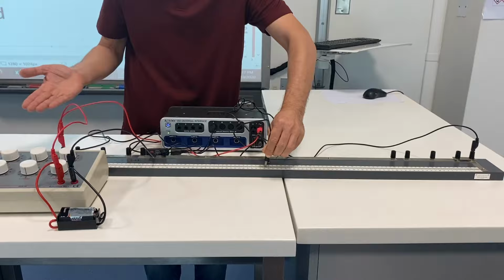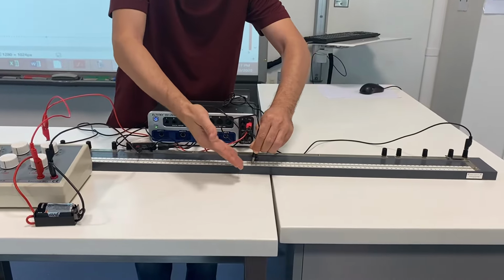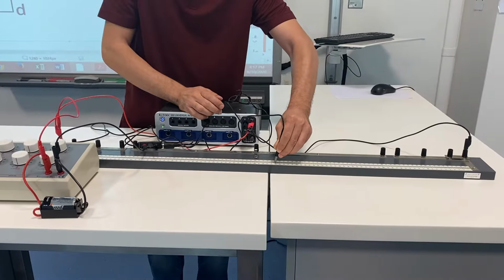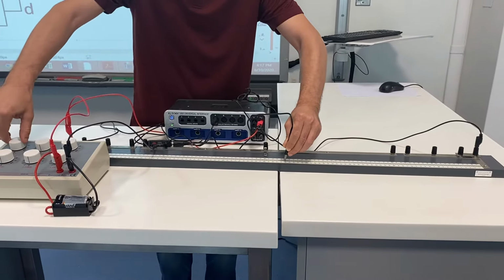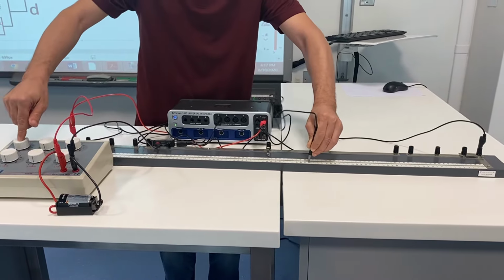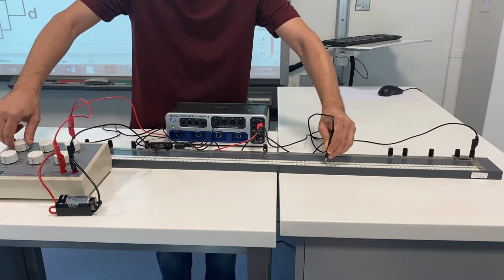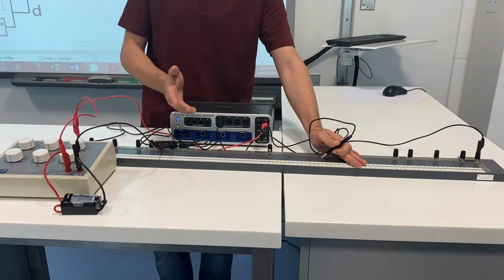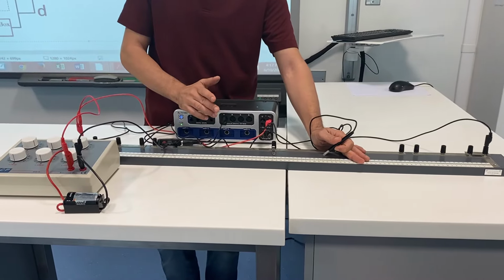You don't have to start from the beginning because the new balance point will be after this. So start from here and search for the new balance point. Then change to 9 ohms on the resistance box, find the new point, and so on. So all of your readings shouldn't need more than 1 minute worth of data taking.